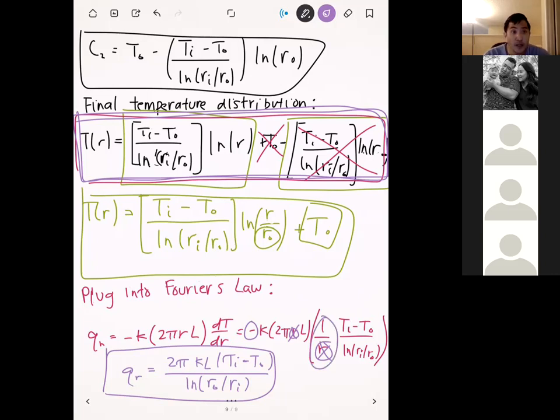And then all the other terms in that expression, the T_o just by itself, and everything in this last term right here, (T_i minus T_o) over ln of R_i over R_o times ln of R_o, all of that is a constant, right? Because R_o is just the outer radius. It's not the actual r function value there. So when we take the derivative of that, that just goes away. And so most of everything goes away except for that first term, and the derivative of that first term is what I have down here. Okay, I see. Thank you. Yep.